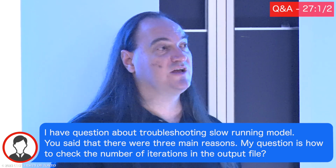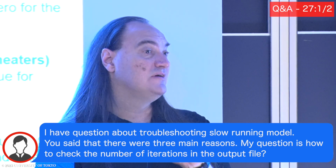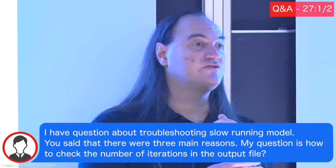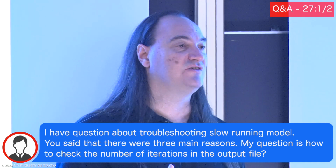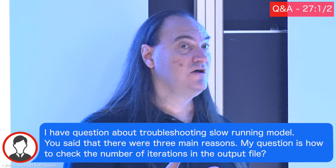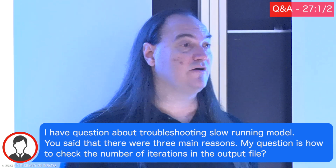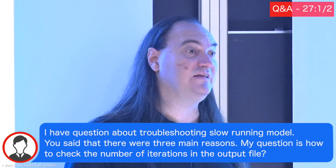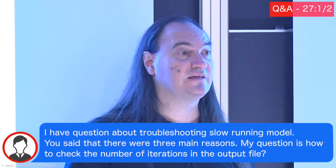The trick is whether it's needing a lot of loops every time step. So one of the things I have is, each time step, tell me how many loops you needed to reach convergence. And I like to look at that and see, is it always about 5 to 10? Are there some times where it jumps up to 50? Does it stay constant? But loop count is a variable that you can output at any time to an output file or a user file or anything like that.